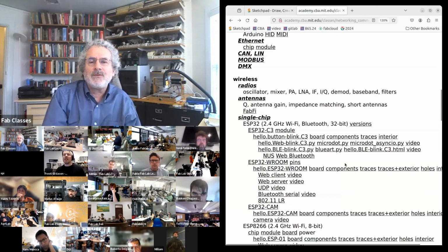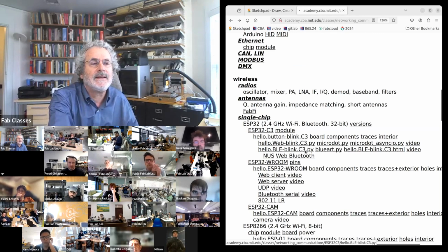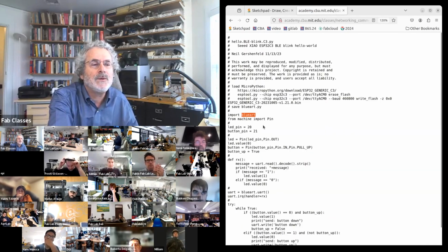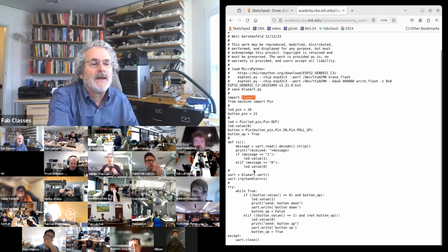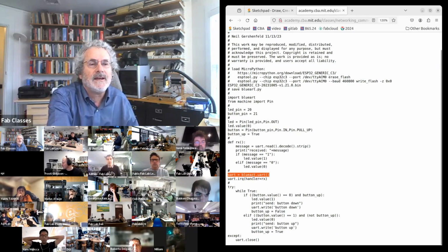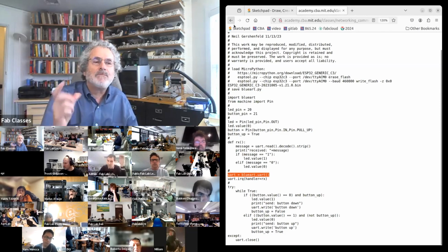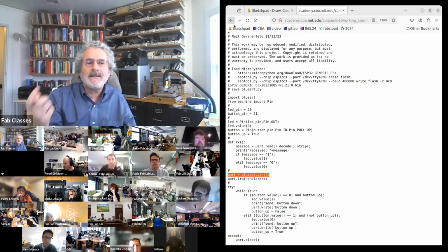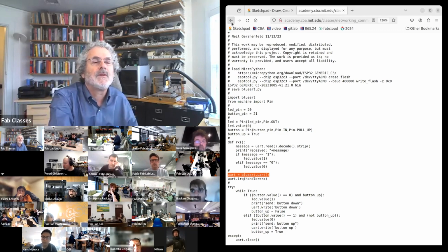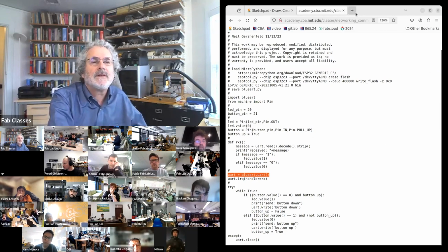So that's taking our $4 ESP32C3. And now I import the Bluetooth library. I start it up as a Bluetooth device. And then the code is really simple. That's all I have to do at that point. Now I'm talking to Bluetooth. And Bluetooth has many different profiles. You can be a heart rate sensor, you can be a speaker.